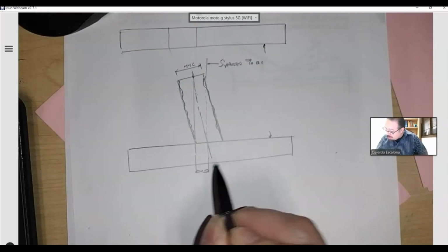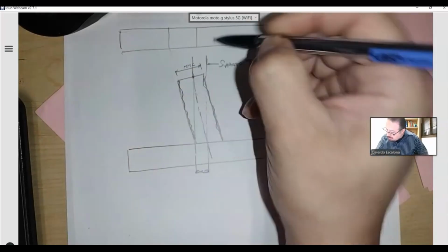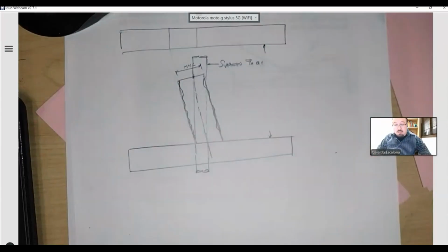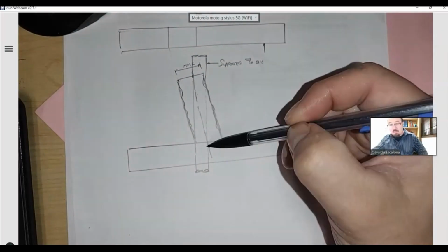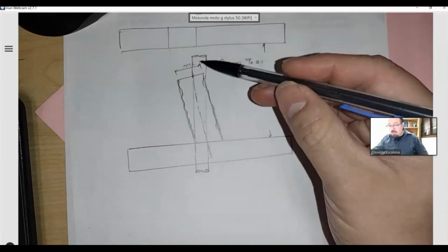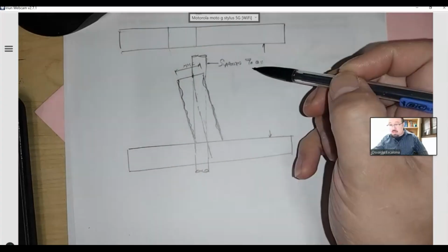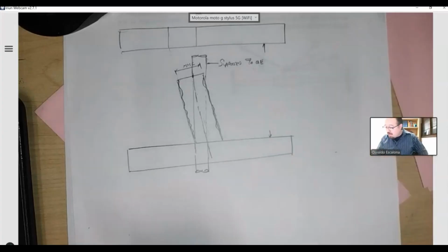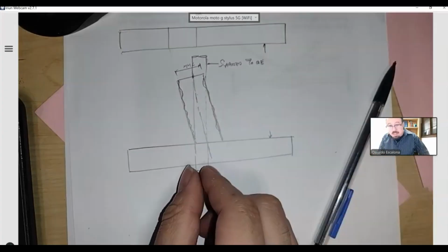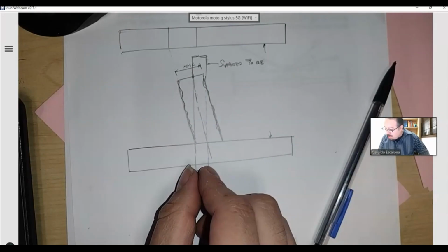And I'm going to put a little zone here. It's represented actually as a cylindrical tolerance zone. My axis that you guys see here, which is actually what is being crooked, has to live within this tolerance zone. This tolerance zone is specified in the feature control frame. Now, if I were to put them both together, I'm going to grab the diameter that I just made, my axis and where it has to live, and I'm going to add them together.